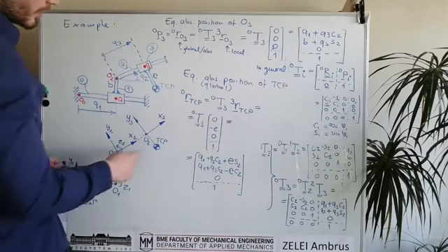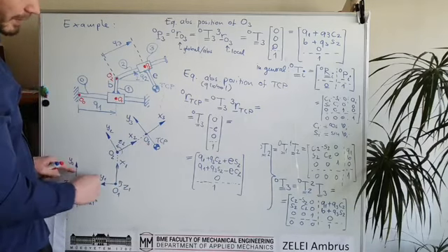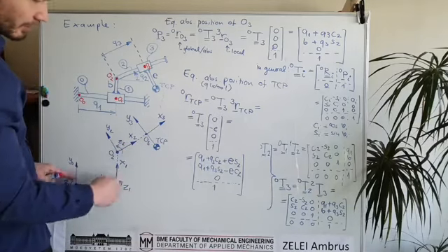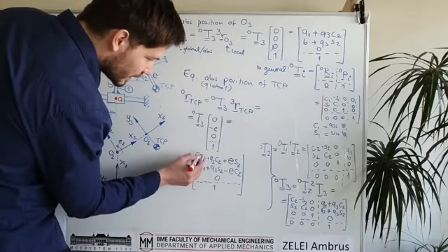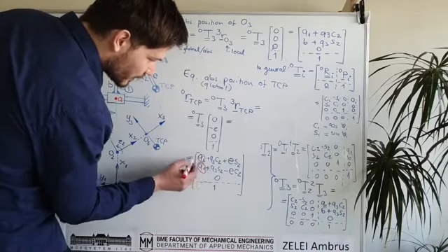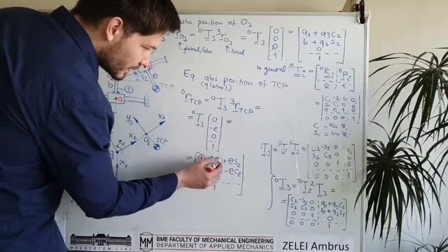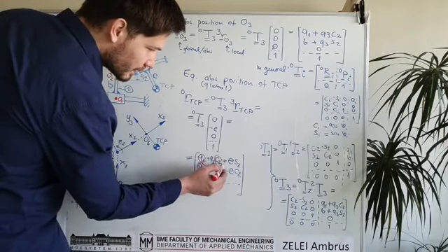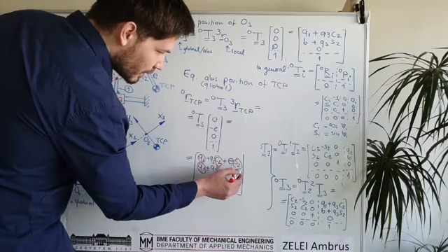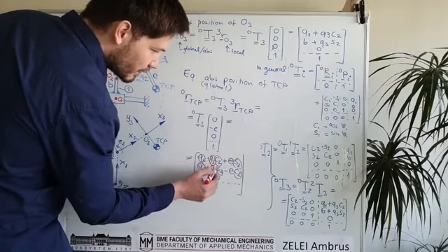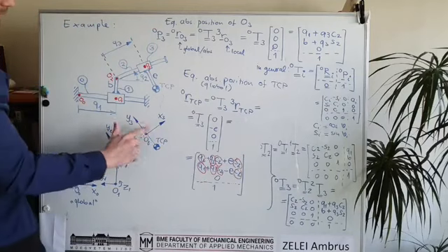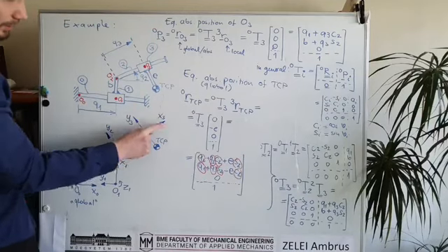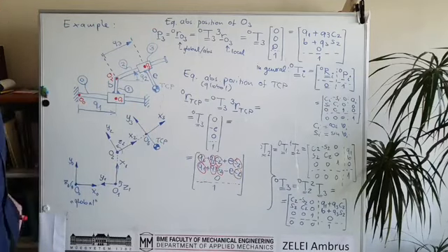Okay, so the position in the global frame is really this one. We can check it by just looking at the figure. And the other important thing again is that it includes the first joint variable, the second joint variable, and also the third joint variable. So we see that the position of the last link always includes all of the joint variables.